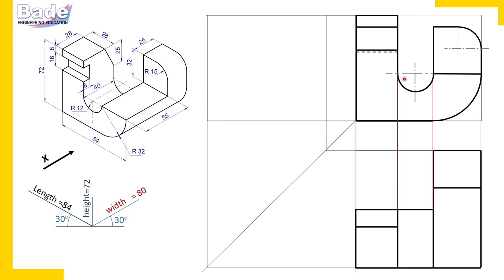Now where a cylinder or semi-cylinder appears as a rectangle, you should draw its axis. So from center, draw a projector to complete the axis of the semi-cylindrical surface. So this is how we have completed the top view. Do you agree? Wait. Watch this surface.